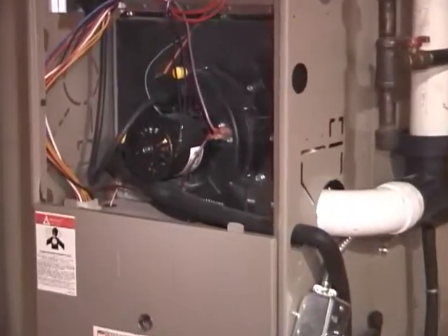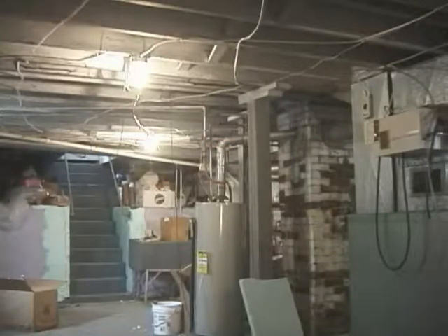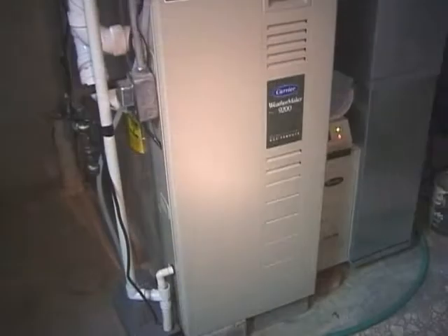The fact that you cannot common vent a Category 4 appliance, such as a 90% gas furnace, with a Category 1 appliance, such as a standard natural draft water heater, is well recognized by the trade. However, a commonly overlooked requirement is that when a new 90% furnace is installed in an existing home, the old standard water heater must be revented with a smaller diameter vent. Many problems can arise from simply leaving the water heater connected to the old, now oversized vent.